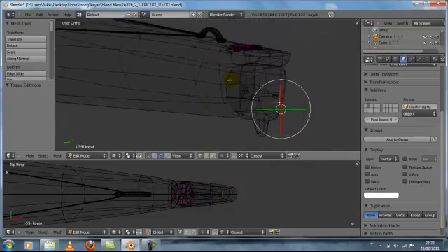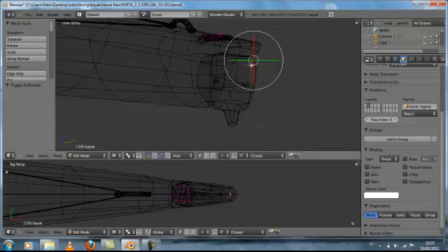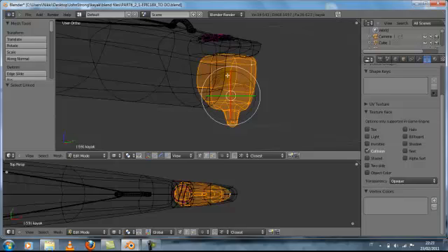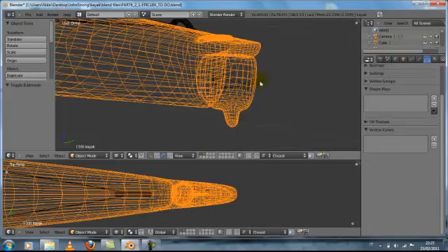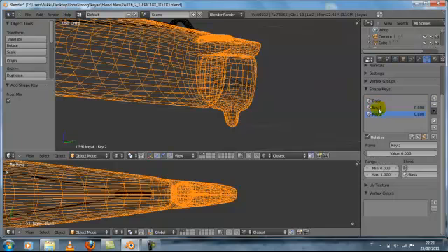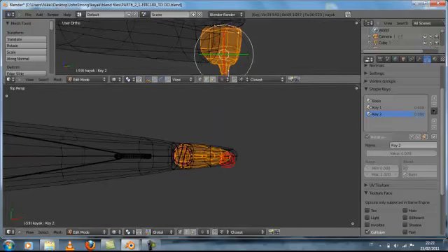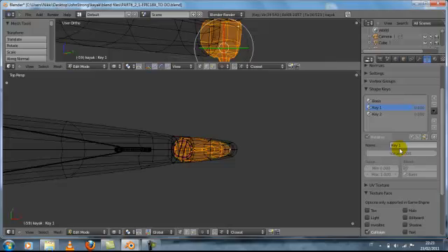What we do now is select the rudder. So just select one point of the rudder, hit Alt to select all the mesh, all the points connected, and go to shape keys. We have to go back to the object mode and create 3 shape keys, the basis and 2 keys. Now the first key, I'm going to call rotate left, while this will be rotate right.